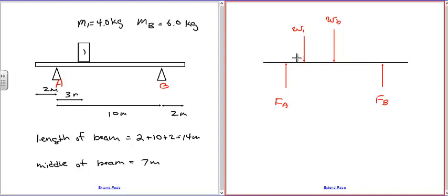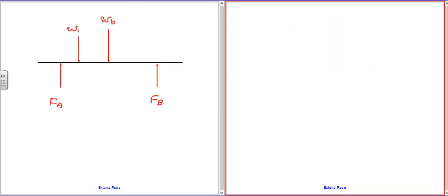You'll see there are no forces acting in the x direction, so we're not going to have to worry about that. That doesn't mean that we never have to worry about that, but in this particular problem, we're not worried about it. Now, here's the tricky part. When you sum the torques, because it's not rotating, there's no axis, there's no axle. So we don't really have a natural point to do the sum of the torques around. So the sum of the torques around any point.